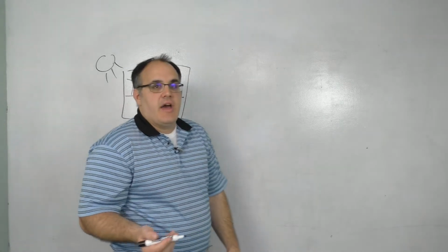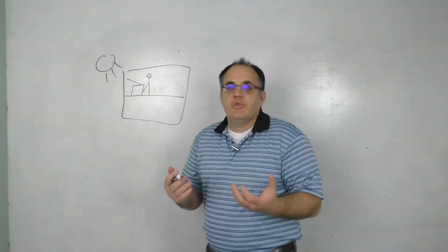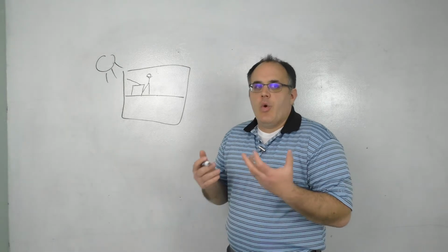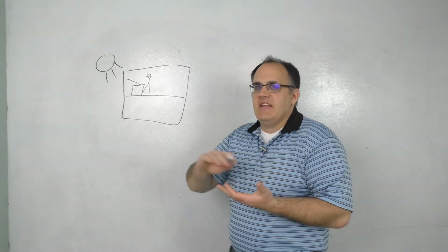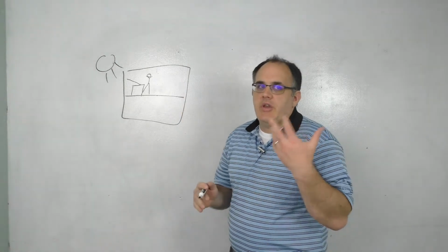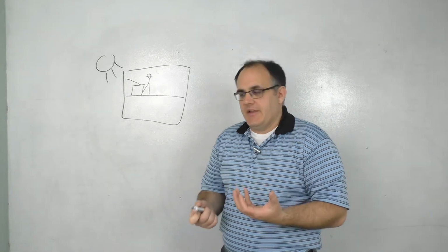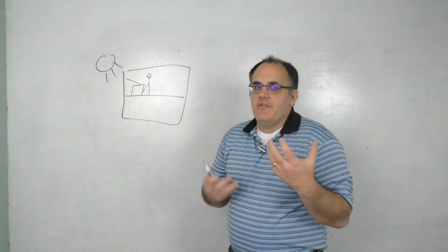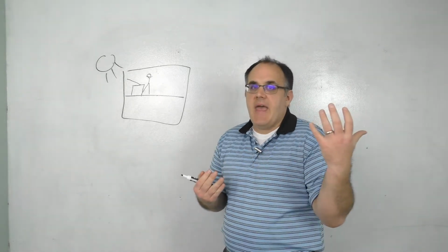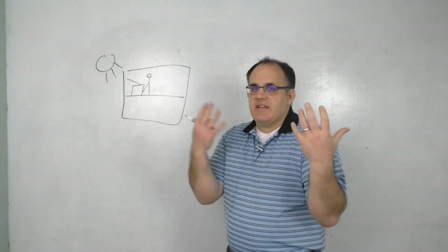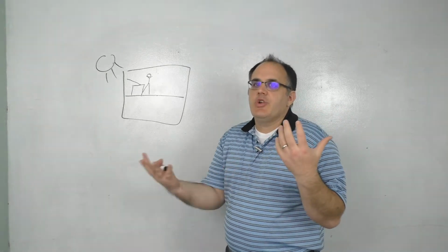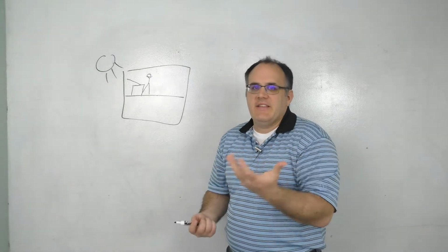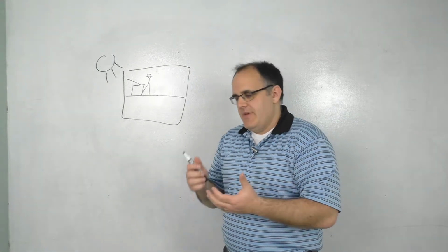Now, another thing you see quite often is where folks will say, hey, I want to stage up my equipment, but I want to stage it piece by piece because I want to avoid demand peaks. Basically, you pay for electricity in two ways. You pay demand and you pay consumption. Consumption is your kilowatt hours, demand is your kilowatt, at least when we're dealing with electricity.